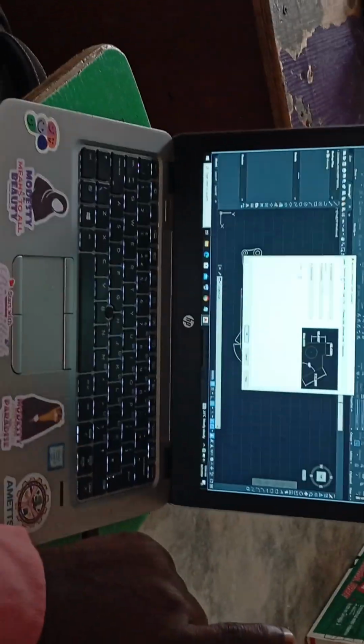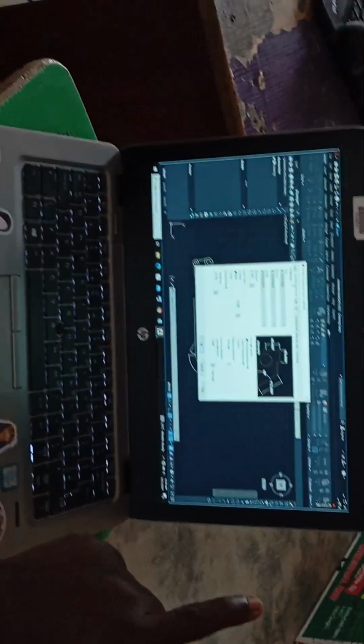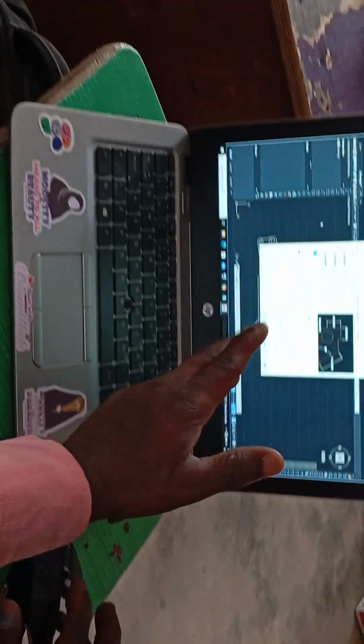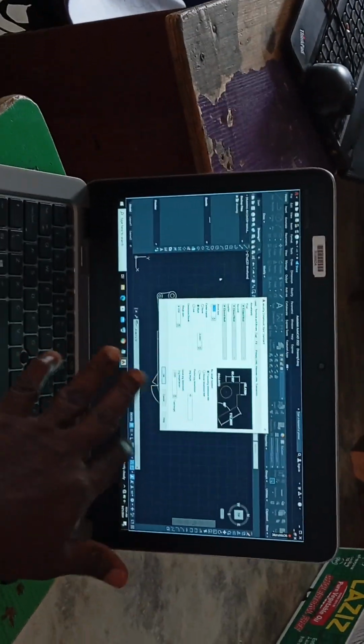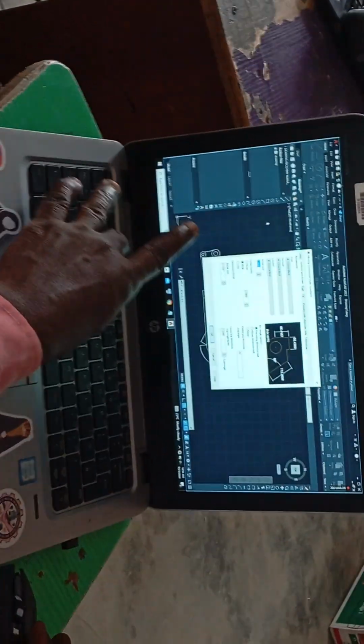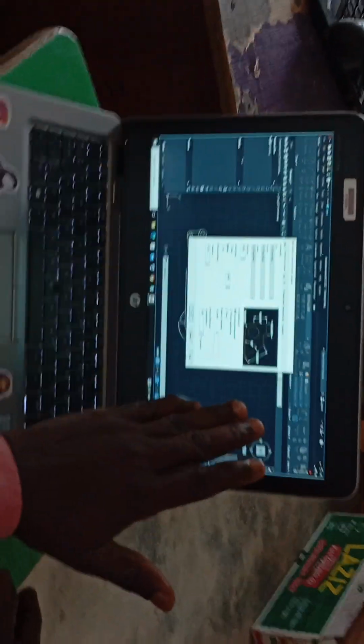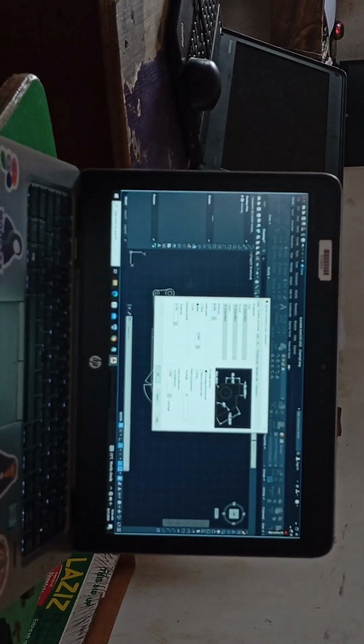Let me now go to symbols and arrows. That's the second parameter to be modified. Arrow size is 0.8. It has to be as close in value to your text height. Let's say we have a text height of 8. Let me give that arrow size of 10. Let me give that arrow size of 8. You see, it will be showing that I'm okay. It will be showing it on this preview section. Okay. After that, any other parameter to set, leave those ones.